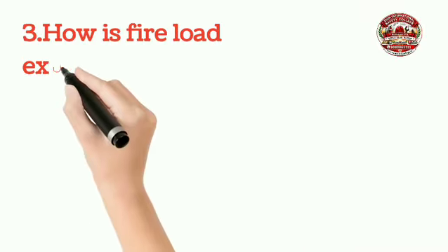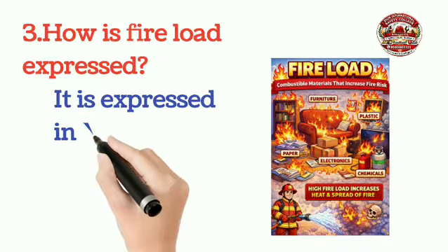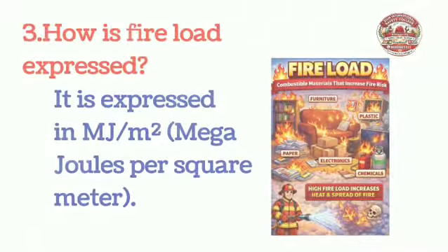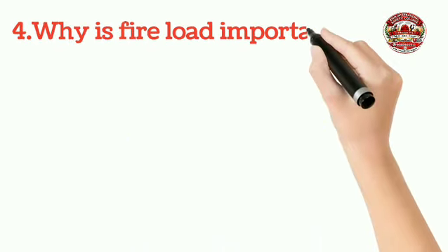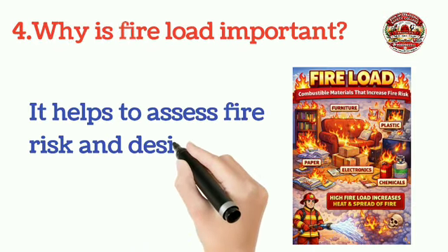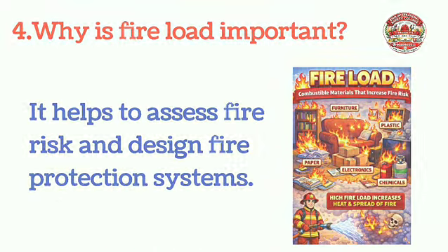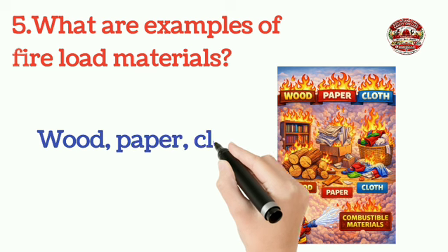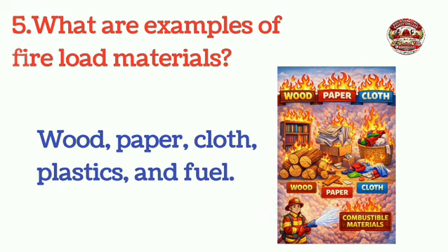How is fire load expressed? It is expressed in megajoules per square meter. Why is fire load important? It helps to assess fire risk and design fire protection systems. What are examples of fire load materials? Wood, paper, cloth, plastics, and fuel.